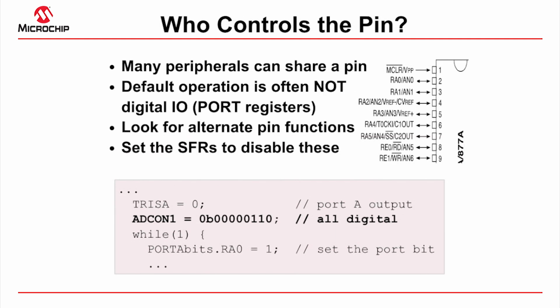The PIC devices have many different peripherals on board. It's amazing how they can fit them all into such a small device. But this does lead to one of the most common beginner problems. Since there are many peripherals, but only a small number of physical pins in the package, the pins are multiplexed, and 3 or even 4 peripheral I/O lines might share the same pin. The device datasheet will typically tag each pin with several labels that correspond to each possible function that pin may be assigned. Some device datasheets also have a pinout description table, which explains the possible functions of most pins.